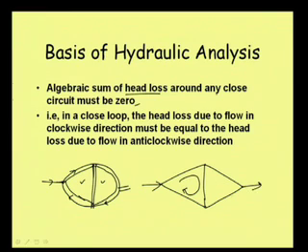Okay. This way the water is going out, Q in, Q out, and there may be another Q out at this point. Well, now in this loop, suppose water is flowing from this side, it is going like this and it is coming like this. Now, this is a closed circuit. In this closed circuit, if we calculate the head loss, from here to here we are getting a head loss. From here to here we can see that water is coming, there will be some head loss in this line, then again from here to here there will be head loss.